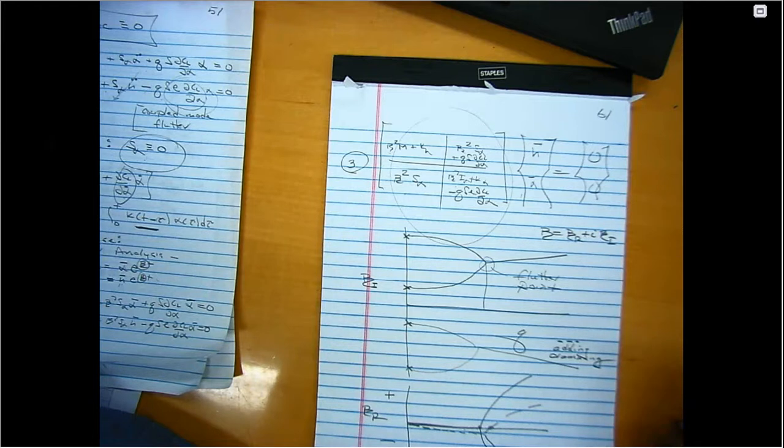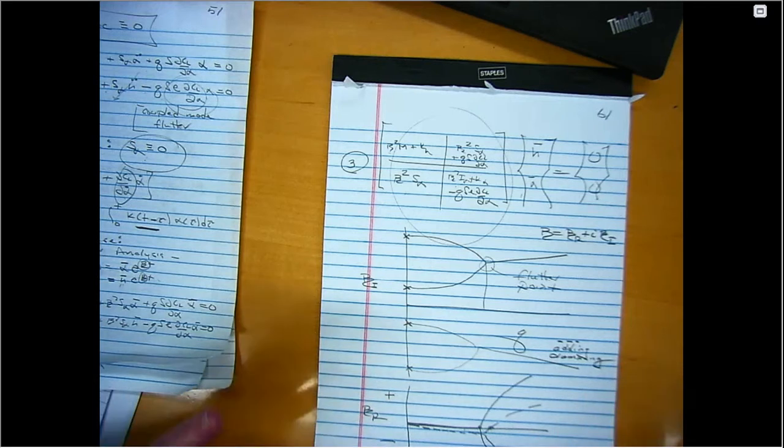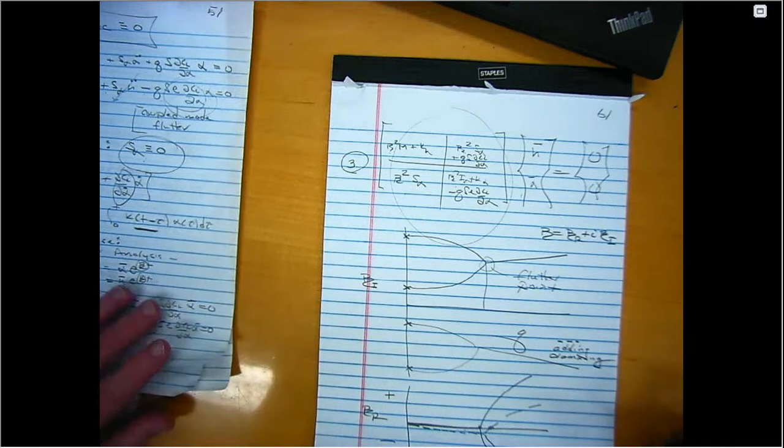It's controversial even to this day whether that's, in the case of structural damping in particular, a physically viable result. Some people say when you have structural damping and it destabilizes the system, it's because of the structural damping. It's not a good model. Okay. But it was a good model when you didn't have aeroelasticity. It was a good model when you just had pure structural dynamics. So why is it all of a sudden I don't like that model? Right? Something people talk about.